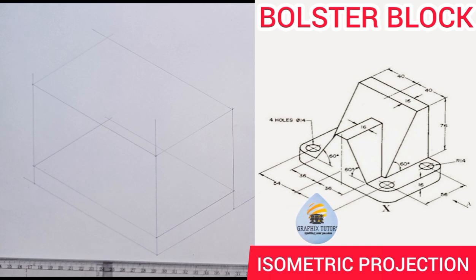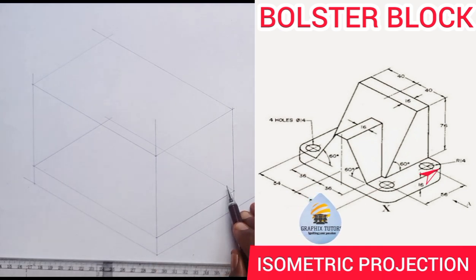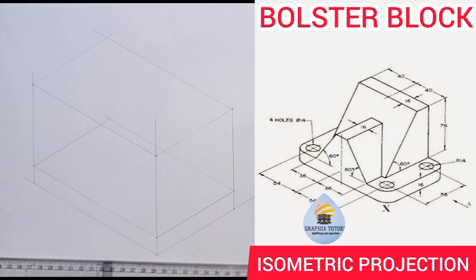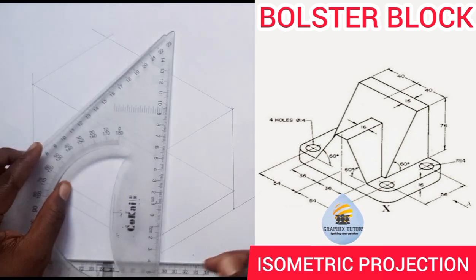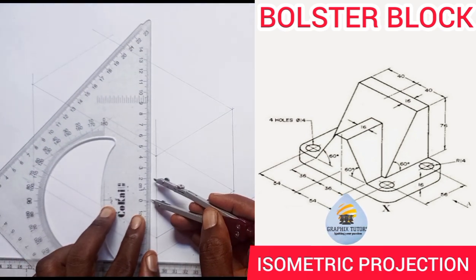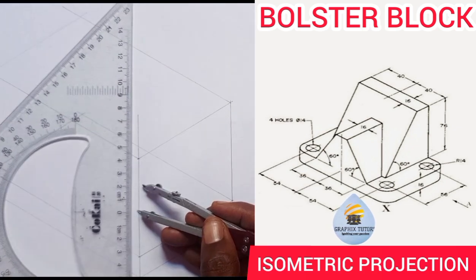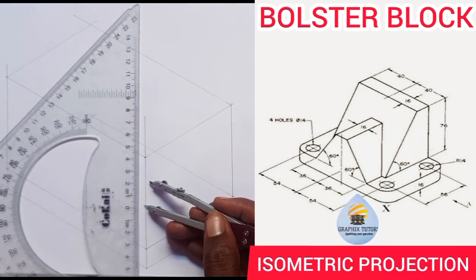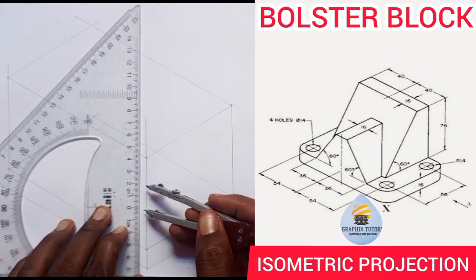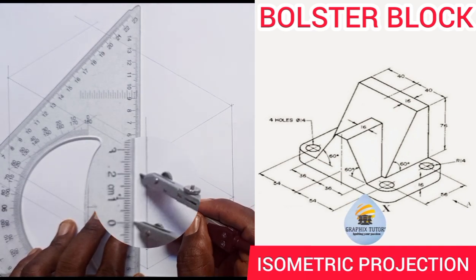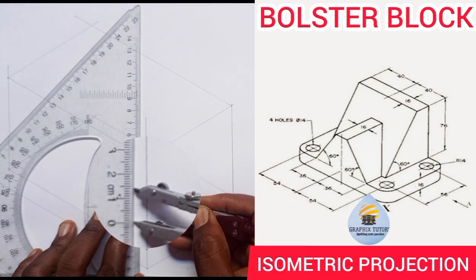Now what do you notice? There are arcs around here. So I'm going to put in those arcs, just like what we've been doing in our previous videos. We have the arc here, it has a radius of 14. So I am going to take my meter rule and measure 14 on my meter rule this way. 14 from 0. Let me increase it so you get to see what I'm talking about. So I'll measure 14 here, 0 to 14. Can you see that?